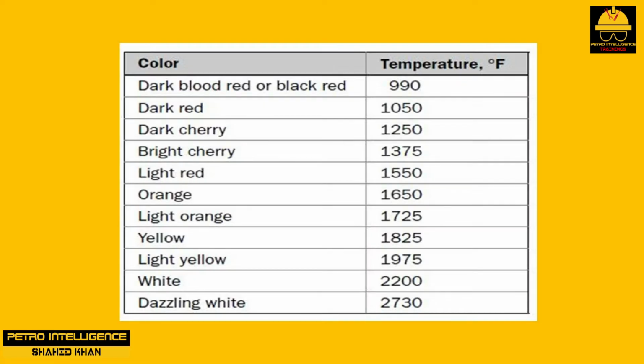There is nothing wrong with a yellow flame; it is the general shape of the flame that is important. Flames should be short and bright. The temperature of the inside of a firebox can also be estimated by its visual appearance, shown in the table.